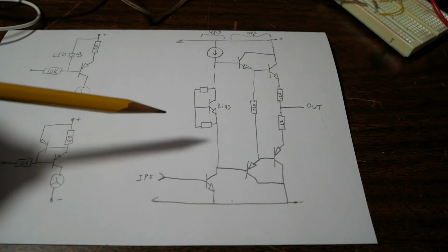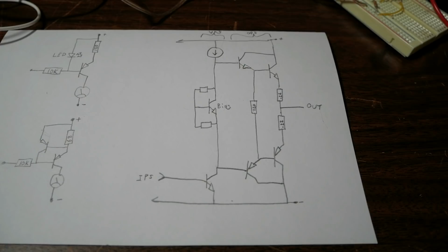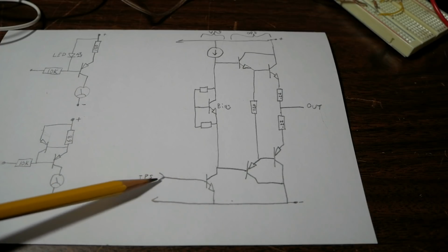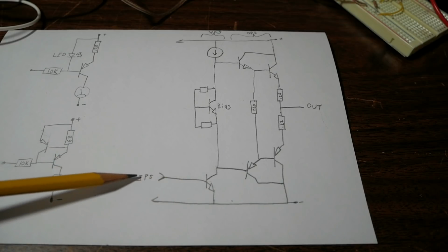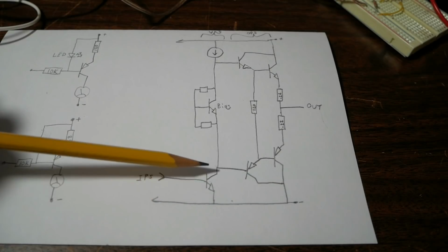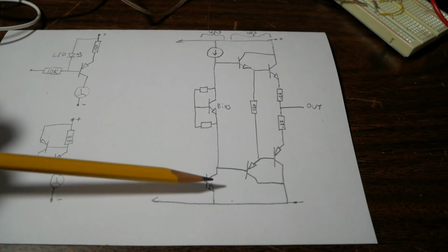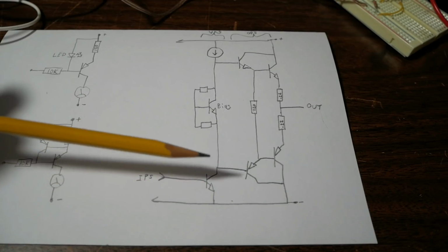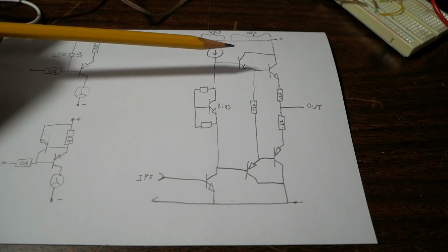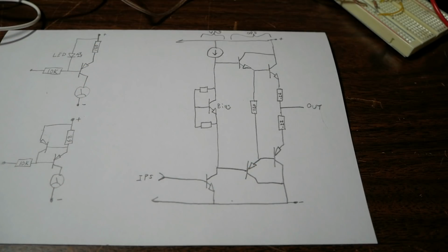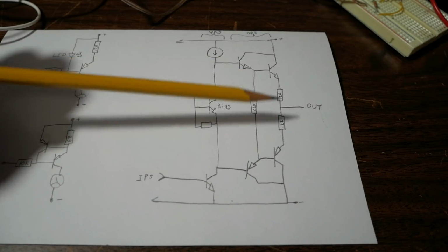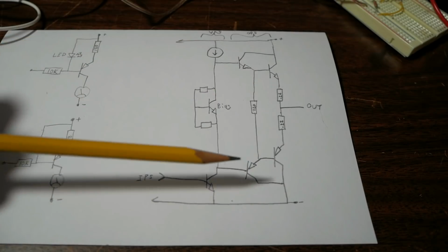So the VAS stage, at least the way I'm going to present it, does three different things. First thing, it takes the signal from a previous stage, in this case from the input stage, and amplifies it through this transistor. This transistor is set up with a class A bias, and it has to make the voltage swing very large. In fact, it has to swing nearly rail to rail. The reason for that is because the output stage doesn't have any voltage gain. The output stage is all about current.